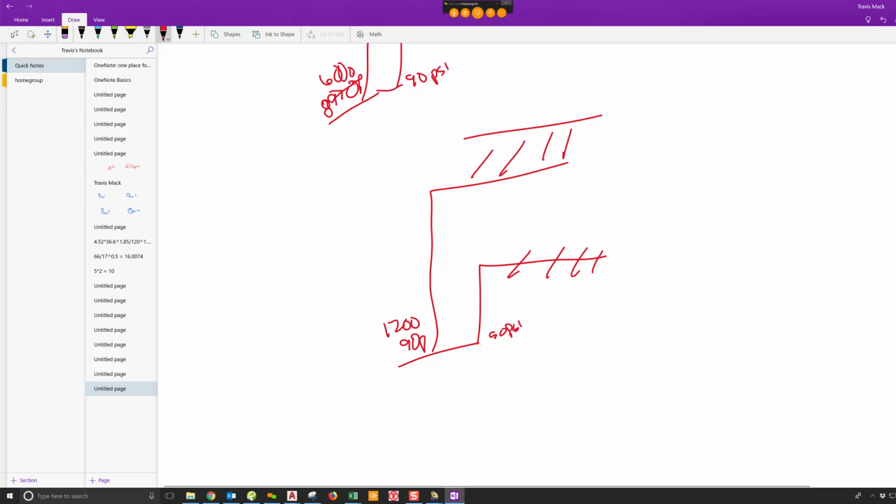needed at this base point here. I'm going to over discharge those racks tremendously because you have to balance to the higher pressure. So what I'm going to do as a good designer, and not being a moron and just always going bigger pipe until the thing works, I'm going to go, hell, I got 40 pounds of pressure that I need to lose in this rack system.